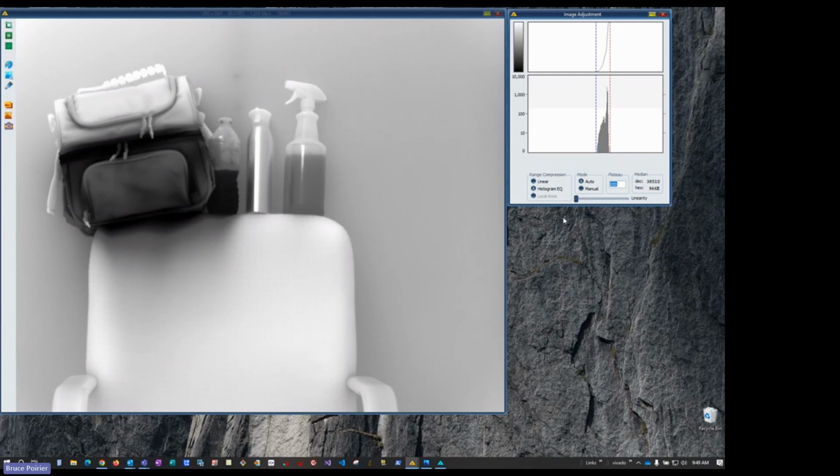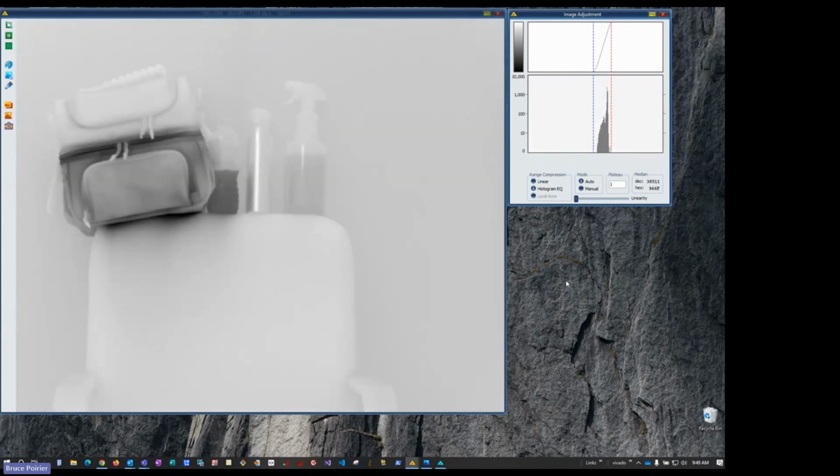You put it all the way down to 1. You can't do 0. Then it's not much different than linear histogram equalization. You see there's a little bit of a dip here, but for the most part, it's linear. So the only thing that we're not applying to the transfer function are pixel levels that aren't counted at all. Like, we don't have any pixels at that level. So that's why there's this little inflection point here. But other than that, it's a linear transfer function.